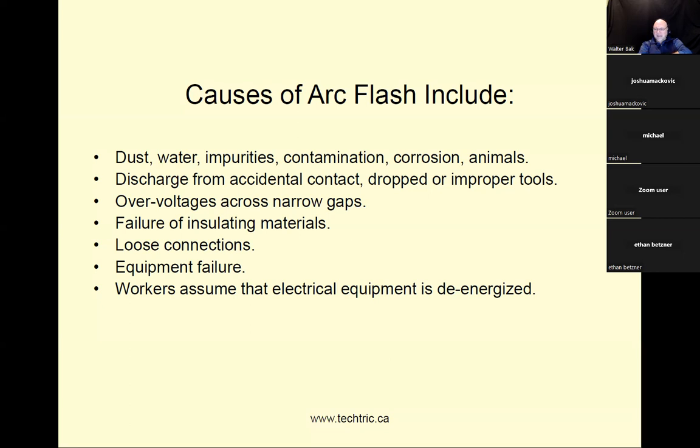If you have enough voltage and enough current, enough capabilities, then it can cause an arc flash. It's just a matter of how much energy can be released when there's a complete dead short between terminals. What's the ampacity? What's the current capability under dead short conditions?